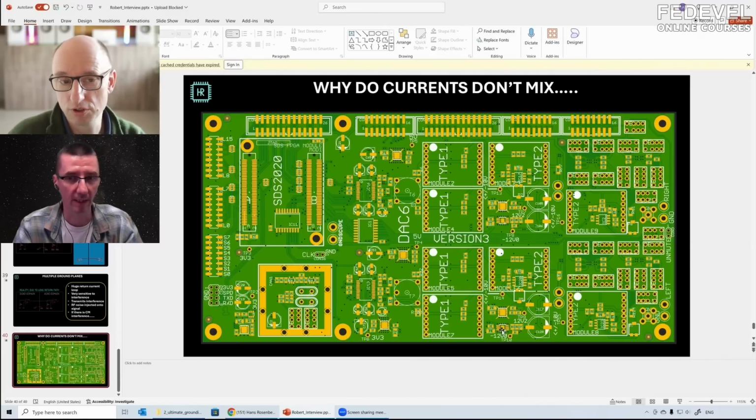You need to be careful how you place, for example, power supplies and these things, because that's what could cross multiple blocks. Yes, exactly. So you don't want to run the digital supply from this connector all the way under here to over there. It has to come from, at least, here. Actually, in this design, all the power comes in here, but the traces are running here. So the return currents will stay nicely away from the analog part.